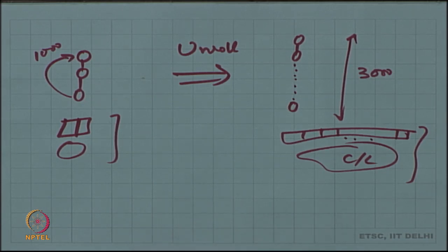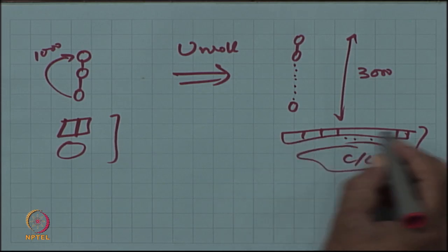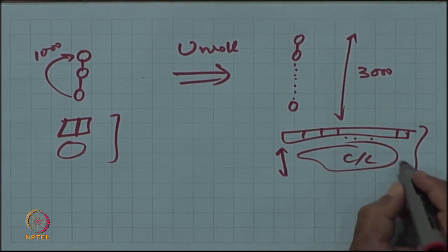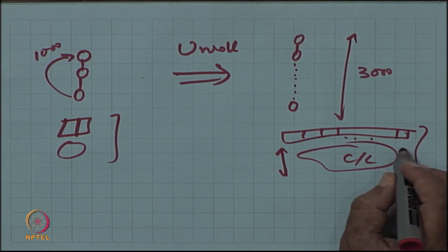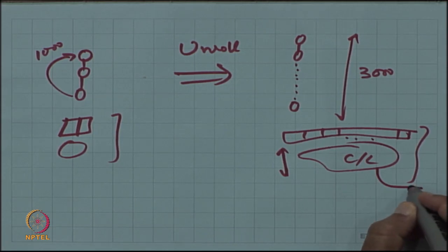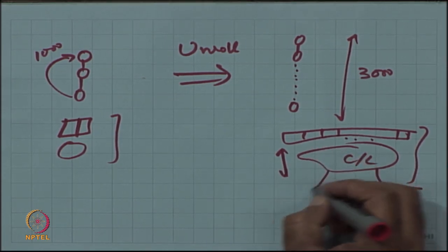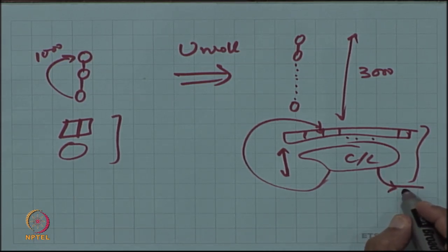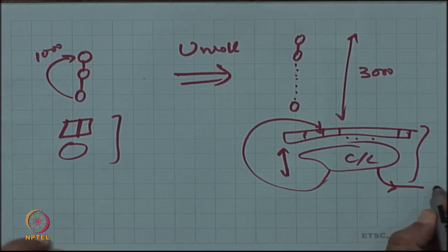Delay through the FSM means this is the sequential part, but this combinational logic, among other things, is generating what output of the FSM? Yes, next state indeed, but what else is going? Next state is the next state logic. Output consists of those select signals, control signals that are going back into the data path, right.